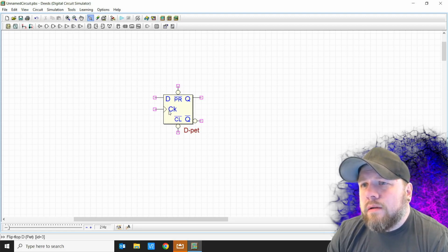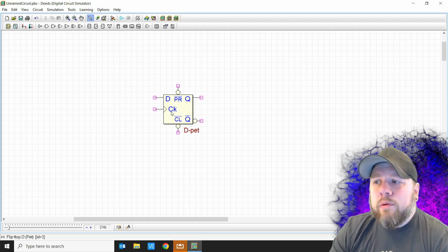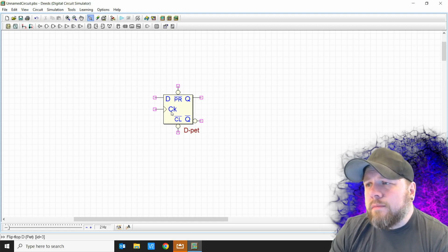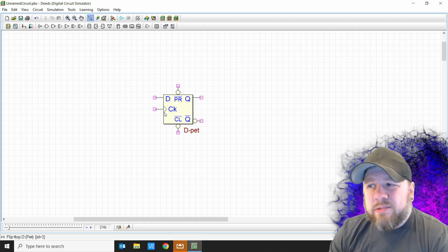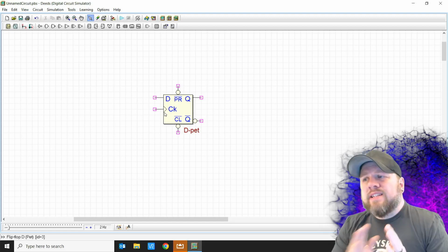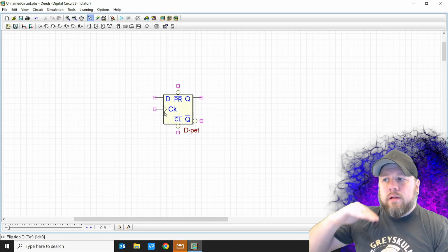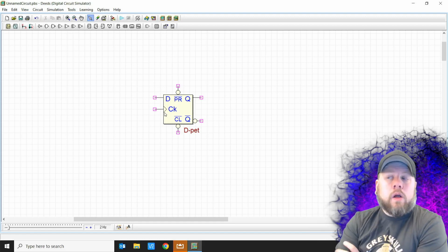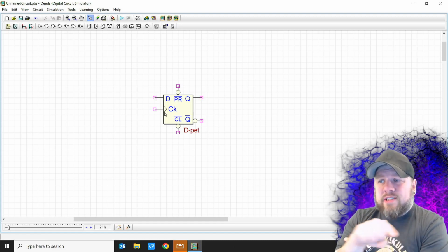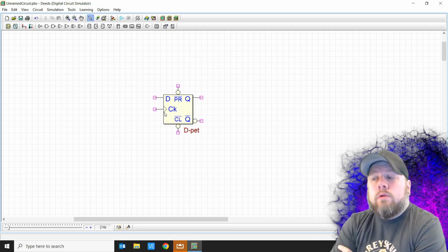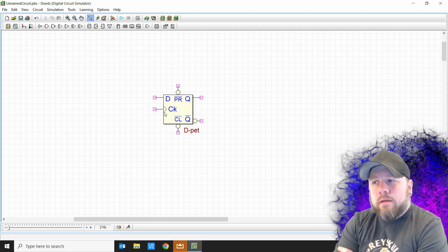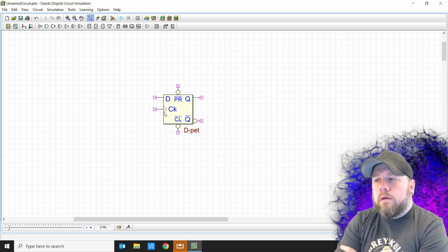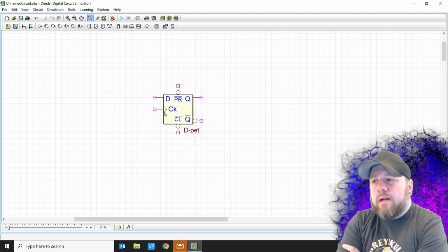is this clock, okay? Instead of having an enable like we built before, it's got a clock, and it's represented by this little triangle. And what that represents really is instead of it being level triggered, it's edge triggered, okay? So if we do a level trigger, that's extremely slow, because a level could be a level for a long time. The transition between low and high is usually very, very quick, okay? So we like to do things really quick, so we like to catch things as they are on edges a lot, okay?